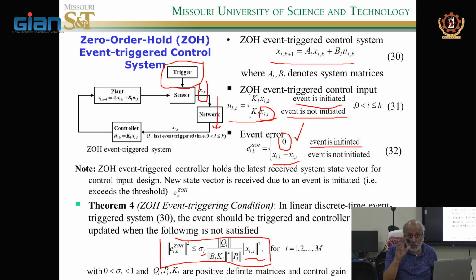So the scheduling protocol has to work less, because each subsystem will have fewer states to send. The sampling interval gets stretched. This is called performance-based sampling, because you are not using Shannon's sampling theorem, that is, sampling at twice the bandwidth.